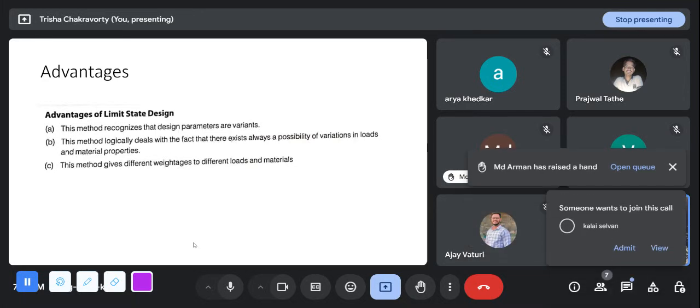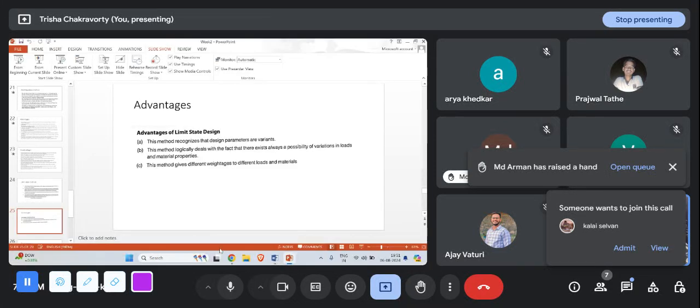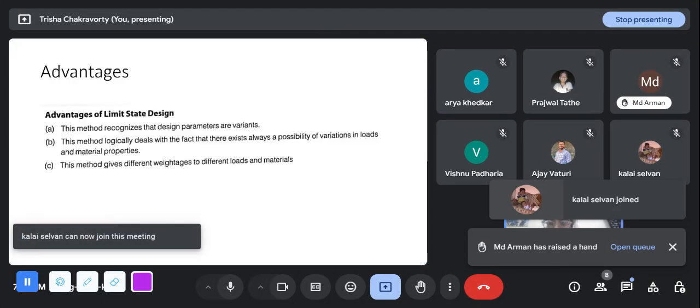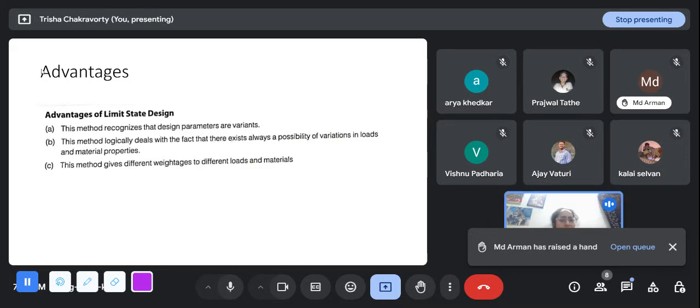So basically, limit state design, by putting a safety factor on the load and on the capacity, recognizes and accepts that there can be uncertainties, and we are dealing with that in a simplified way of just multiplying or dividing by partial safety factors. Now how these partial safety factors come has to do with the area of structural reliability. We decide that we want this much safety of the structure, and from there are methods to decide upon what the safety factors will be. As we vary the safety factors, the reliability of the structure increases or decreases.